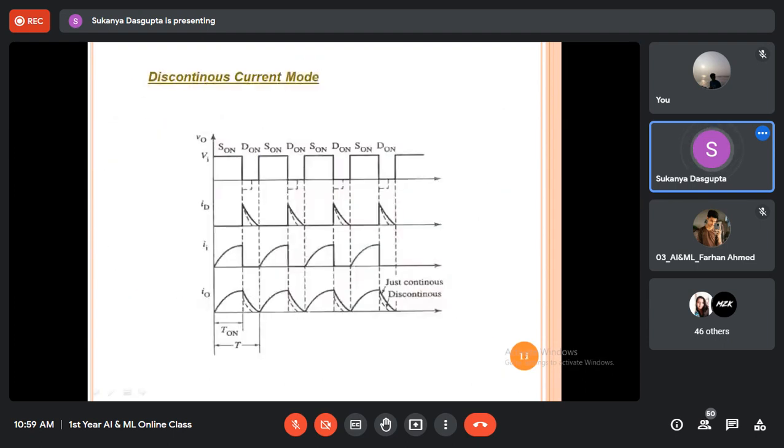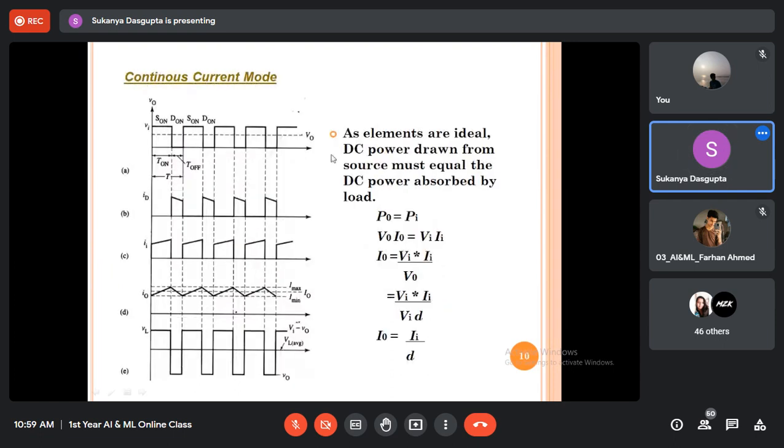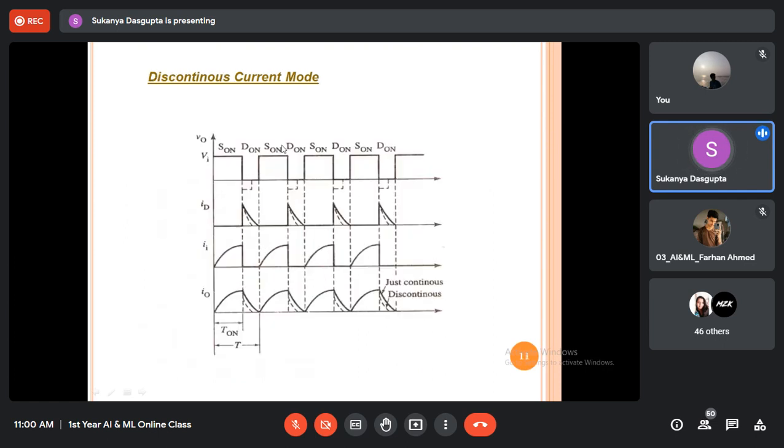Look at the expression of output voltage, graphical response of output voltage. It's a pulsed signal. The dotted line is showing just the average value, right? But if you want to measure the RMS value of the output voltage of buck converter, how do you calculate the RMS voltage? The solid line is showing the actual output voltage response curve of buck converter. It's just a pulse signal.